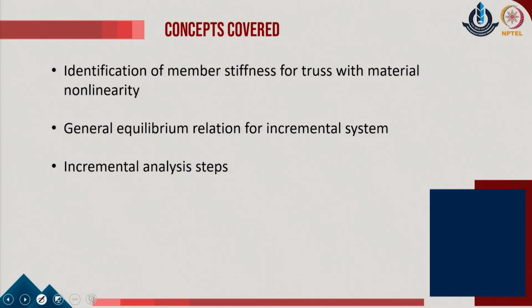And as we go with the problems of unloading, the specific cases of how the material follows the behavior with the load reversal, like the manner of the kinematic or the isotropic hardening, as well as the point from which the initial material starts to be unloaded, all those parameters also become important to be evaluated. The plastic strain component also remains one of the important aspects of the analysis, and we came up with some of the standard relations towards the end of the last lecture.